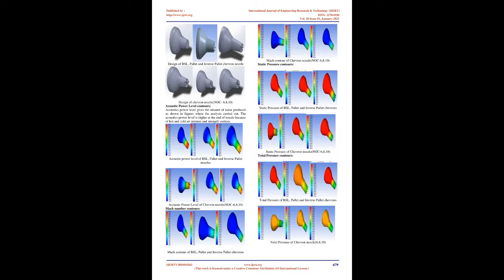The numerical studies have been carried out using a validated steady 3D density-based implicit, standard k-epsilon turbulence model using standard wall functions. This model uses a control volume-based technique to convert the governing equations to algebraic equations. The viscosity is determined from the Sutherland formula. The nozzle geometric variables and material properties are known a priori. They do the modeling of those various types of nozzles. For the analysis, at the exit, a far field boundary condition is prescribed. Ideal gas was selected as the working fluid.